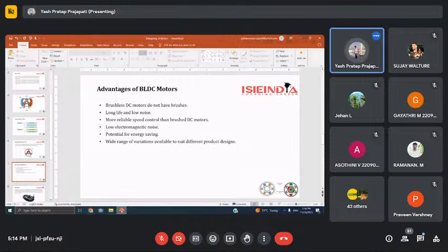And what is the future of BLDC motors? We can expect to see BLDC motors used in a wider range of applications in the future. For example, they will probably be widely used to drive service robots, small robots that deliver services in fields other than manufacturing. One might think that stepper motors would be more suitable in this type of application, where pulses could be used to precisely control positioning, but BLDC motors are better suited to controlling the force.